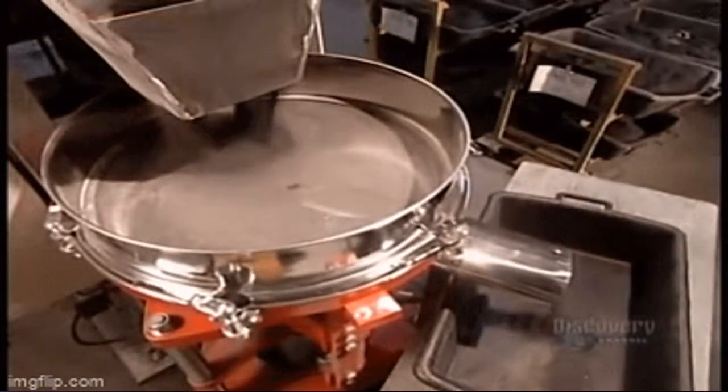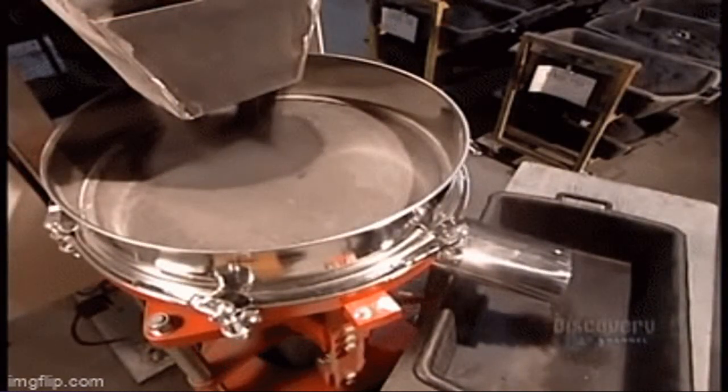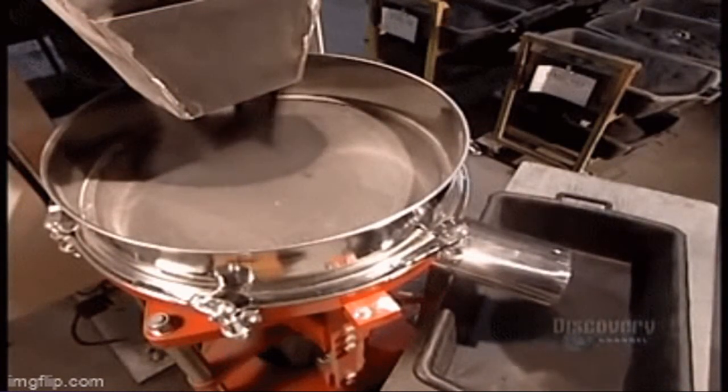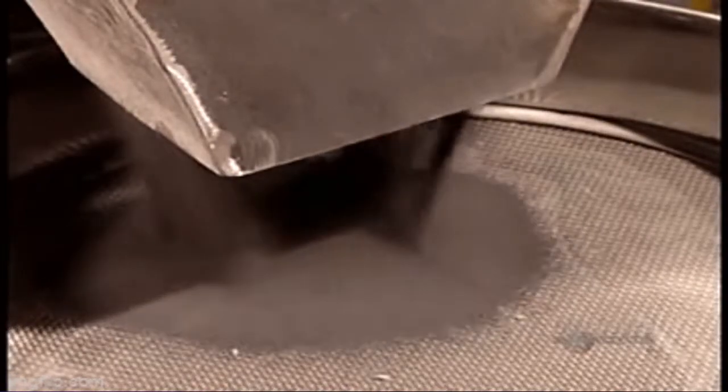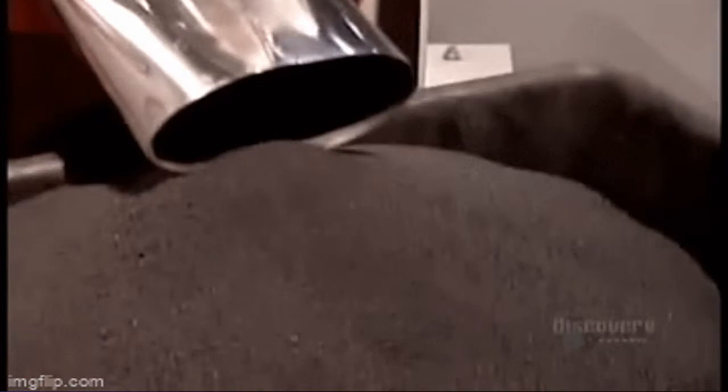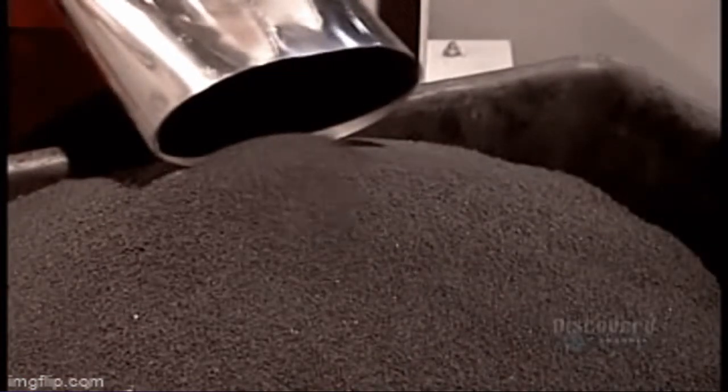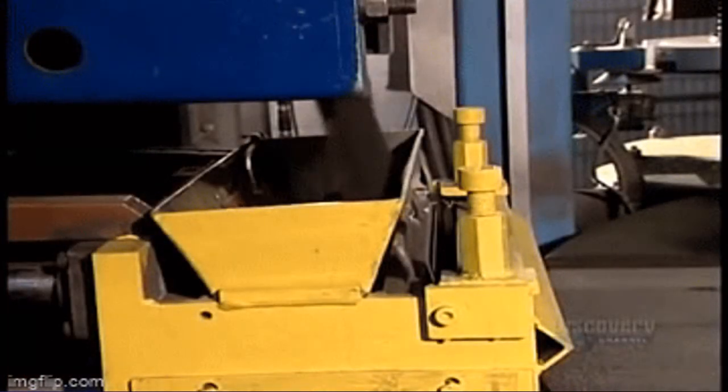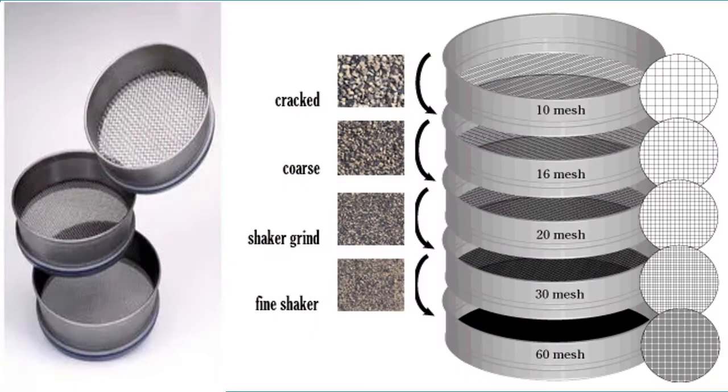The grit size is measured using the screen mesh procedure. In this procedure, a smaller grit size has a larger number and vice versa. The grain sizes used in grinding wheels typically range between 8 and 250. Grit size 8 is very coarse and size 250 is very fine. Even finer grit sizes are used for lapping and super finishing operations.